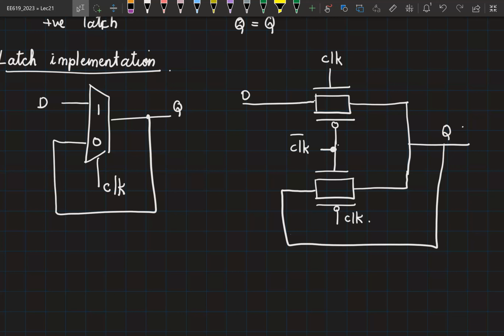You need the capacitance at what node? Okay, is that sufficient, or is the drive strength information missing? You also need to know what is driving the D input, right? So in practice, when you put this in a circuit, this will be driven by some gate, right? So that information is now missing, which means, what estimate can you make about the current available?